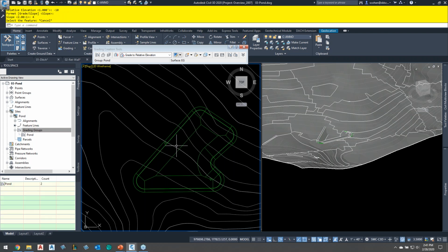Now, again, as I mentioned before, actually, I'll just leave it. I won't do the infill just yet, and you'll see what happens. And then we'll go ahead and click on this here. We'll go to grade to surface. And then we'll click on create grading. And then we'll go ahead and click on the outside here. Yes, for the entire length. For a slope of 4 to 1 in cut. A slope of 4 to 1 in fill.